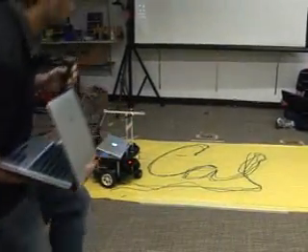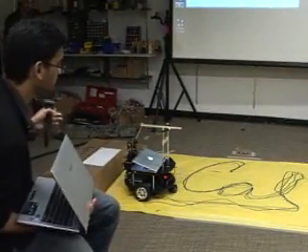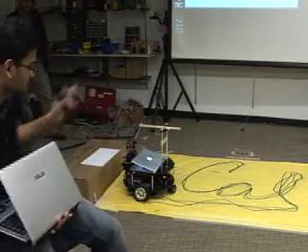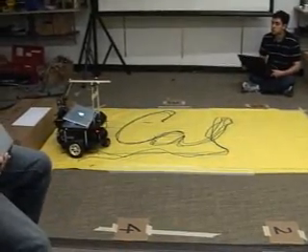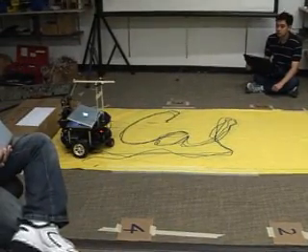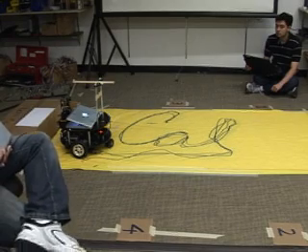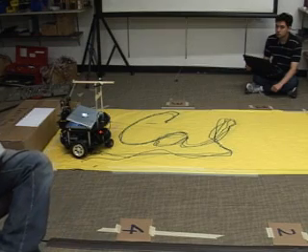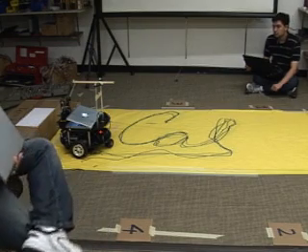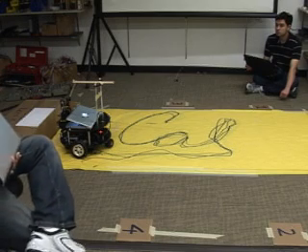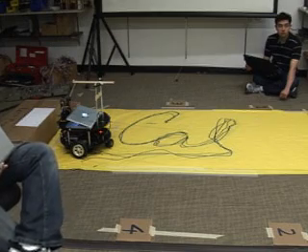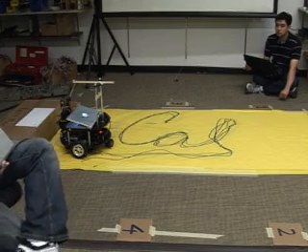So in the path planning, the first priority is least distance. As you can see from here, chef's table, 1, 2, 4, chef's table is the equivalent to chef's table, 4, 2, 1, chef's table. So the additional optimization, I should say, is after that. Since we have these 2 equal optimal paths, the robot will consider the one with what is called the least order infractions. So even though table 1 ordered first, table 2 and 4 ordered soon after. So the priority would go to servicing 4 and 2 before 1, which is why it chose to go 4, 2, 1 and not 1, 2, 4.